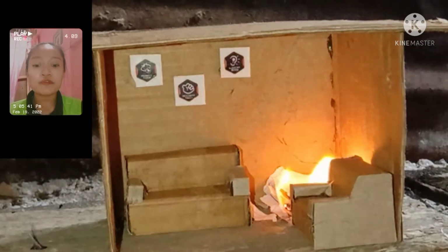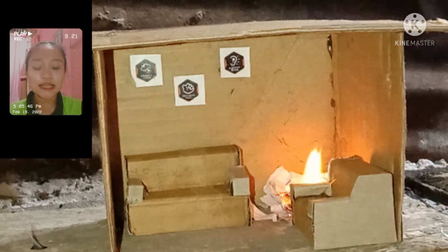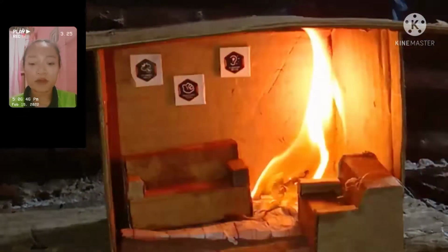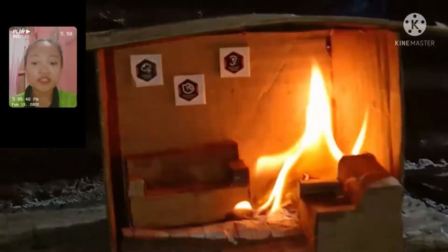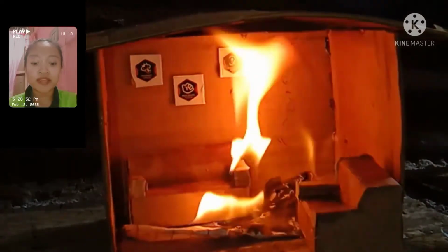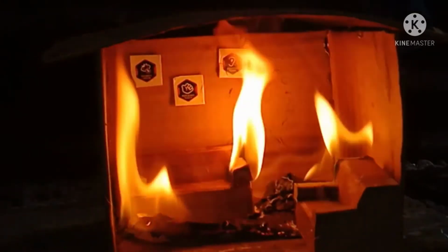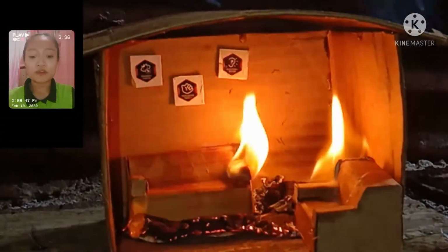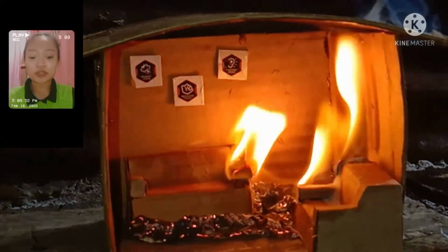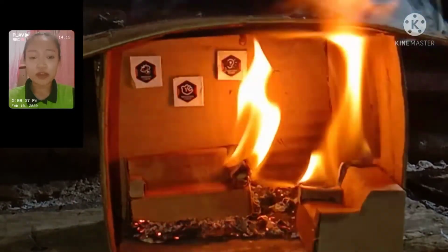As you can see, the fire started on the back porch with a piece of newspaper. It burns clean for the first few seconds. And once the fire gets into the synthetics, we see fuel-rich combustion products pouring out and filling the hot gas layer. Notice the piece of crumpled newspaper on the floor in the center of the room. As we start to get a rollover, the hot gas layer radiates heat to everything around it.